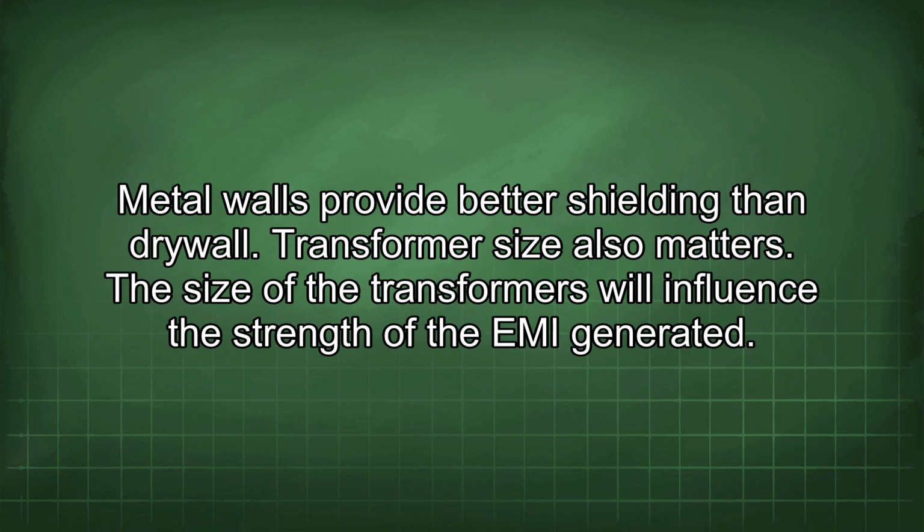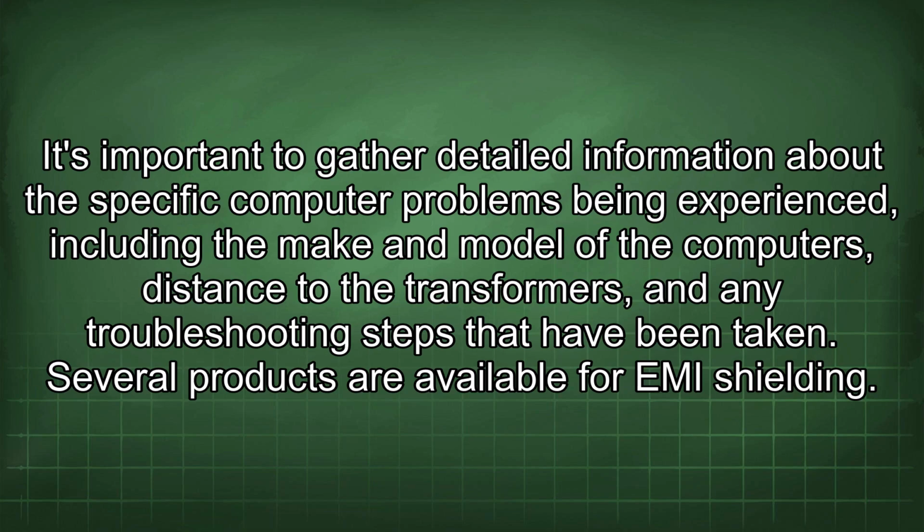Transformer size also matters. The size of the transformers will influence the strength of the EMI generated. It's important to gather detailed information about the specific computer problems being experienced, including the make and model of the computers, distance to the transformers, and any troubleshooting steps that have been taken.